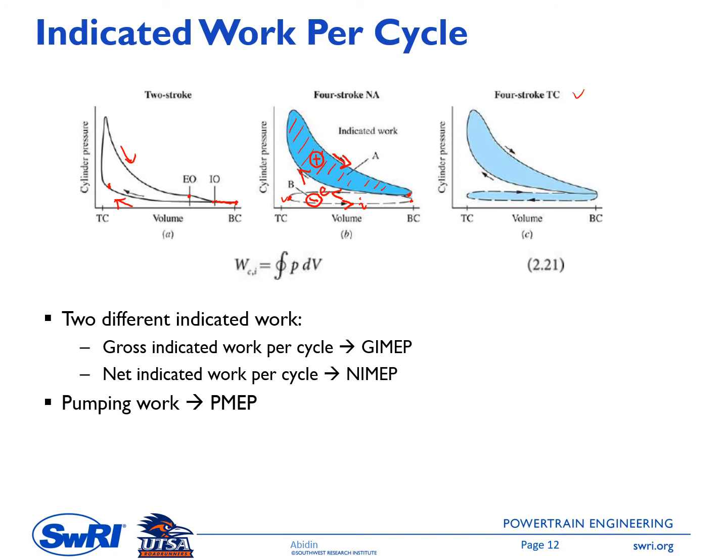This results in increased cylinder pressure during the intake stroke compared to the cylinder pressure during the exhaust stroke, represented by this feature. This one is for the intake stroke. You see here, the pressure line is above this pressure line, which is during the exhaust stroke.